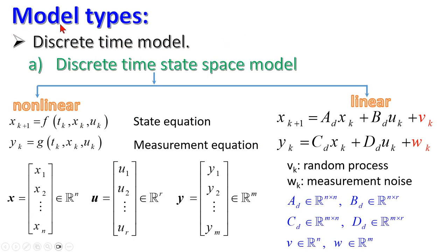We will first start by looking into the first part, which is the first meaningful term, the model. There are different types of models that are suitable to be used with MPC problems. For example, state space models are very much suitable to be used with MPC. Also, input-output models are very well suited to be used with MPC problems. In practice, MPC is implemented in a computer or a microcontroller, which are digital devices. So let's first start with discrete-time models. In discrete-time models, let us start with the discrete-time state space model.